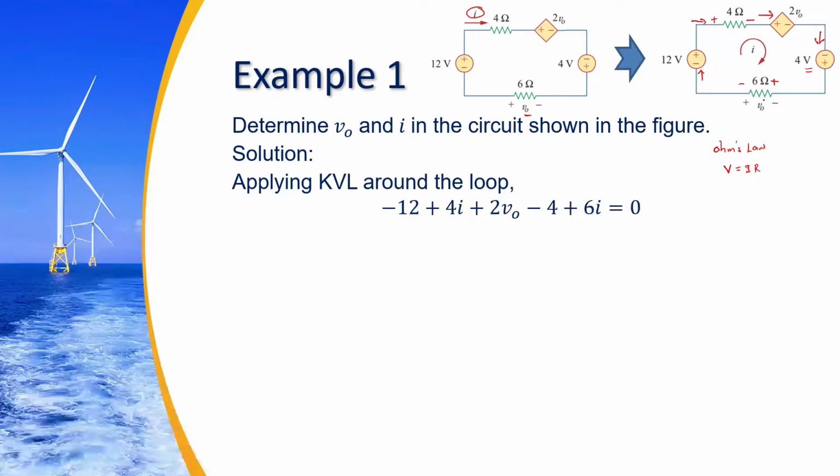Next, pagdating dito kay resistor 6, pagpasok ng kuryente dyan, ang makikita is positive, kaya siya plus 6I. So, bakit may I? Kasi resistor lang siya, hindi pa siya voltage. Para maging voltage, i-multiply mo siya sa current natin na I. Okay? So, therefore, lahat na yan is naka-voltage. And then, sabi sa rule natin, lahat ng voltages na yan, kapag kinuha mo yung sum, ang equivalent niya ay 0. So, that will be our equation 1.1.